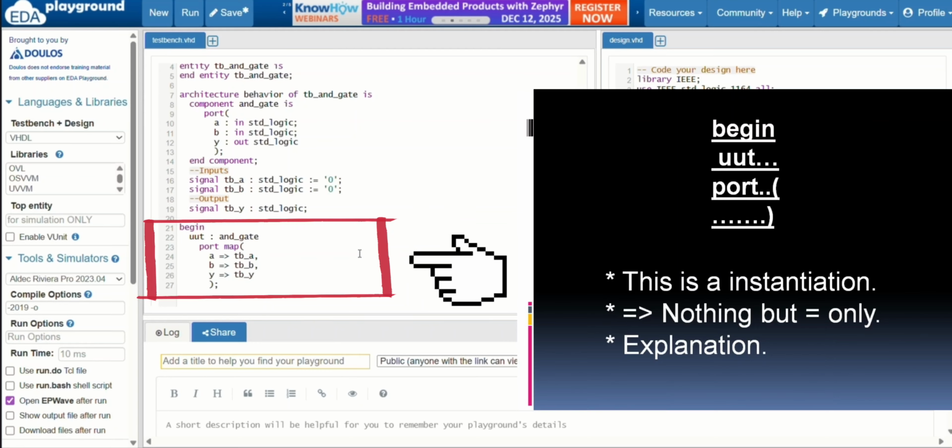Your test bench will run. Your stim_proc will send signals through the wires tb_a and tb_b, and an oscilloscope will record the results. But because there is no AND gate connected, meaning the design that has been present is not connected to those wires, the output tb_y will never move.